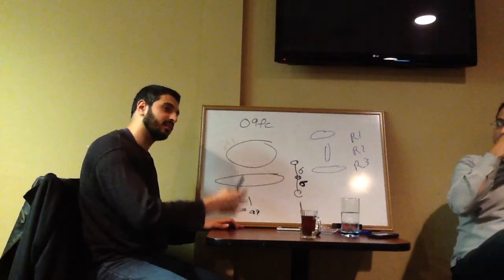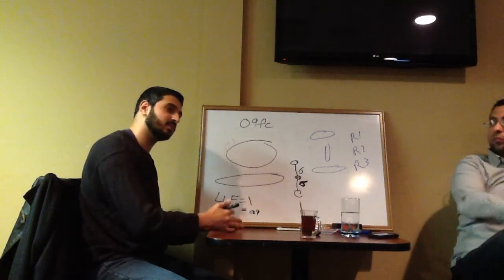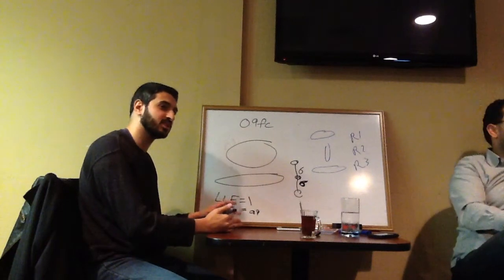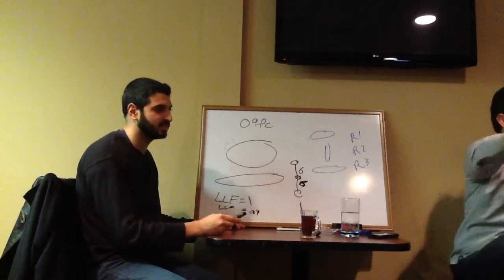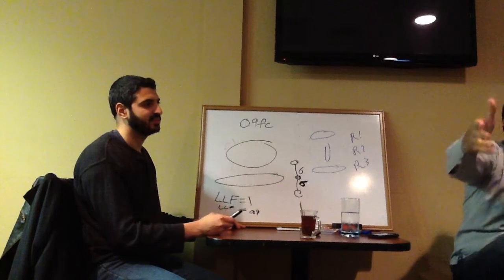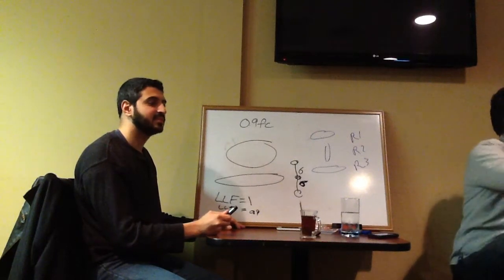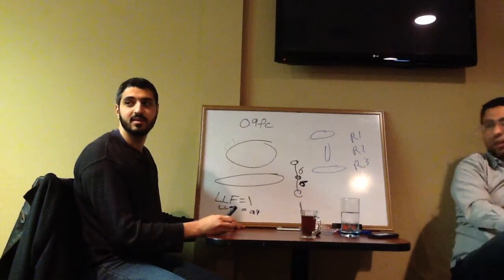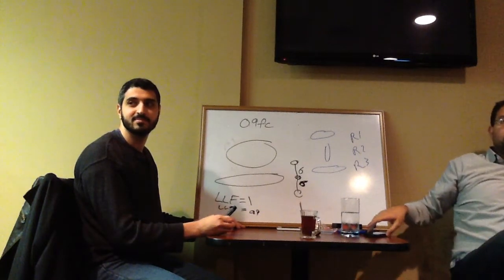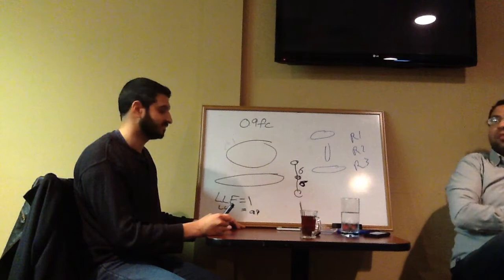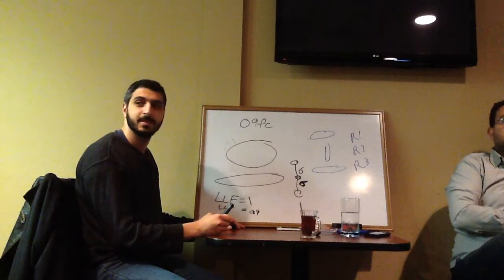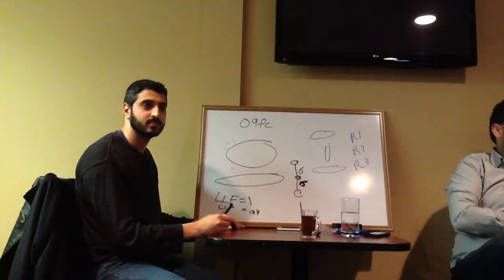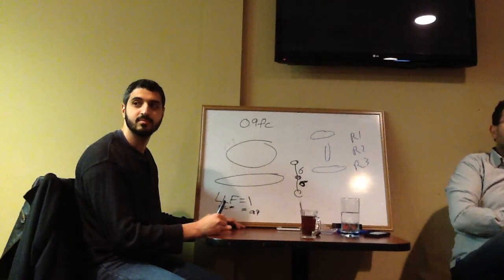From testing they figured it's going to be 0.6, 0.7. Let's say the light is sitting for 10 years. After 10 years, from their experience, it's going to be 0.7, almost half the output. So this is really the degradation in the performance of the light. The light is not going to be as bright, as strong, as good as on the first day you put it in. With time, it's going to lose its intensity.